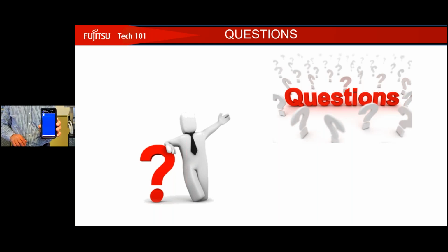I apologize if this looks a little wonky. We're doing our best. So I'm picking a wall mount, okay? And I'm clicking done. Now at this point, it's showing me, if I have a wired remote, I can click on that to see what the error code is, or I can go to my indoor unit LED. Those are the 3 flashing lights on all of our indoor wall units. So I'm going to click on that.